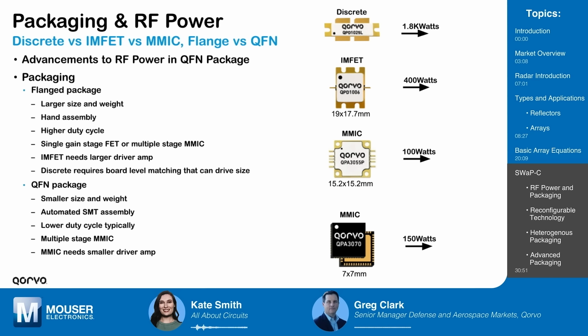Yeah, maybe. Yes. And from a system standpoint, in order to get the gain up, you're distributing your gain. So you maybe need a smaller driver amp versus a larger high gain amplifier to drive the FETs. But the other thing that shows here from a slide perspective is 1.8 kilowatts. That's low frequency. The very bottom one is actually an S-band part. It's capable of 100 watts, and 150 watts is what we're driving towards. Moving up to X-band, you're seeing 100-watt capability. And that's not just from Qorvo. My competitors out there are doing the same thing.